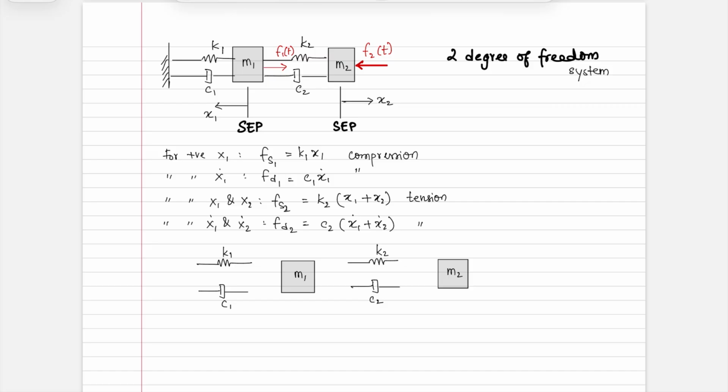We now want to go from left to right, defining all of the forces. So in the first case, it is in compression. You capture that first. One good thing about drawing it in the exploded view is that you can always visibly see when you're forgetting any of the reaction forces. So here you have FS1, FS1, FS1, FD1, FD1, FD1.